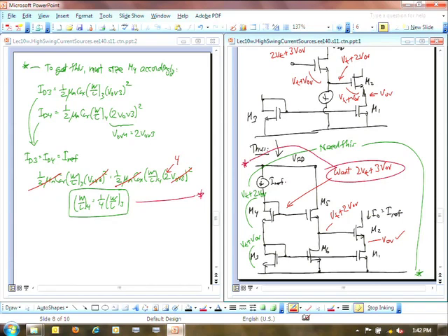So it's not the actual capacitance. It's just right in the mu n Cox. So the VT we'll have to talk about in a second, right? Because we'll have some VT issues here that we'll have to look at. But if there were no VT issues, this would be the equation you would use, 1/4. But in actuality, we're not going to be able to do 1/4 because of the VT issues you're mentioning. Basically, a transistor will end up not in saturation if we do this. But let's get to that point.